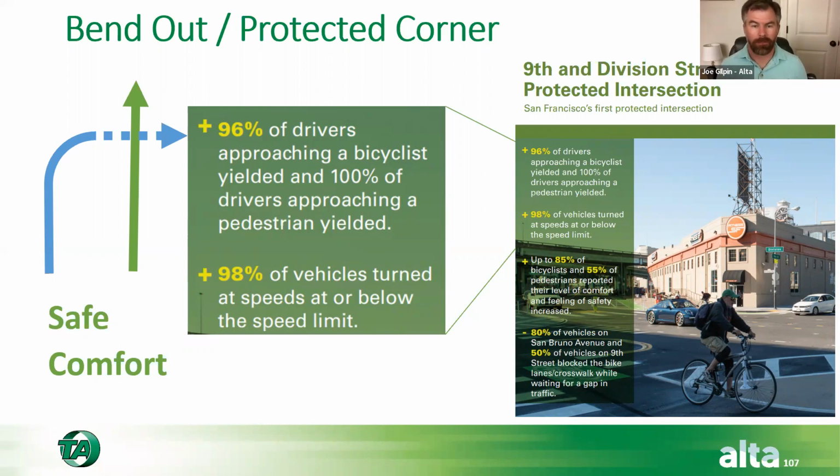There's an alternative type of intersection approach that I don't have any pictures of here, but NACTO is pushing it, and where you don't have enough space to fully set back the bike lane, they're claiming it's still worth it. And again, we don't have data on this yet because of that problem that we talked about earlier, but they call it a dedicated intersection. You would bring the protection up to the intersection, keep the vehicles out of the bike lane, but you wouldn't have that setback. You would have an adjacent crossing at that point. I don't know, again, is that safer? I know that it's more comfortable.